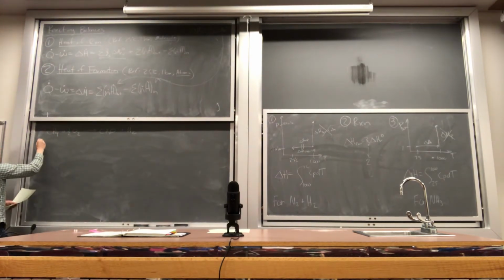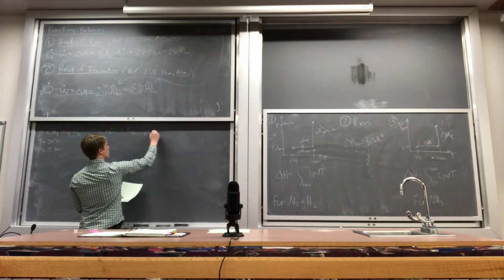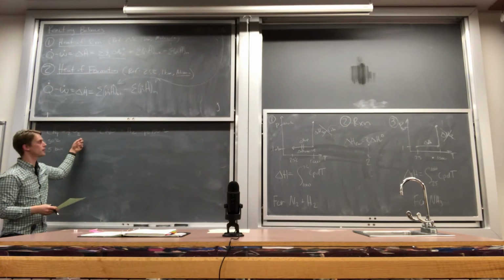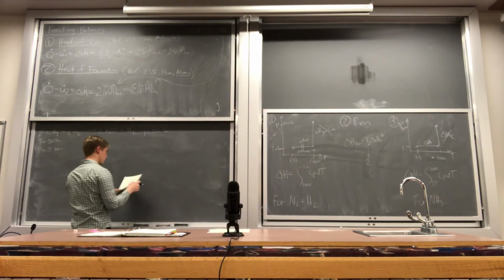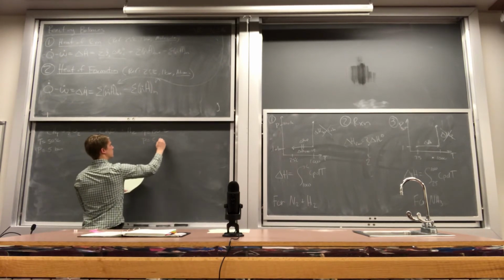But in this case, the feed is going to be at 50 degrees C, and the pressure is 5 bar. Leaving the system, it's going to be 150 degrees C, because this is an exothermic process. Well, it is with methanol. I don't actually know what it is on this one here. And the pressure, let's just say, is 5 bar as well.